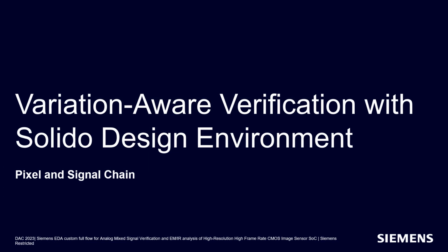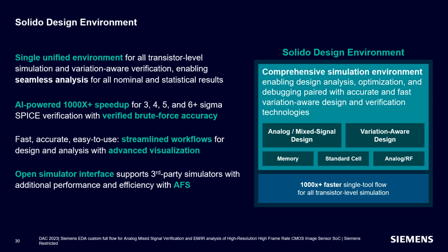Next, we discuss how Siemens Solido design environment helped us to efficiently and accurately quantify the effect of process mismatch on circuit performance. Just a brief context on the Solido design environment, or SDE. It's a unified environment for all transistor level simulations and variation aware design verification across all statistical process corners. The AI powered engine speeds up any statistical variation with up to 1000x speed up compared to brute force accuracy.